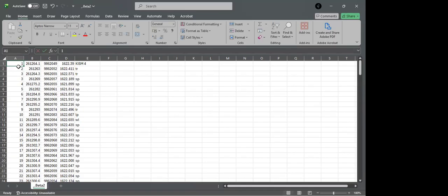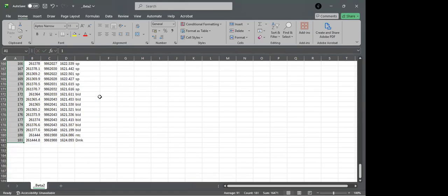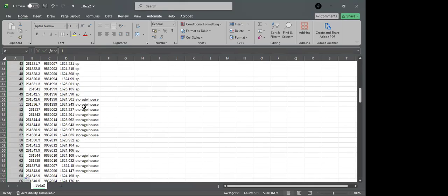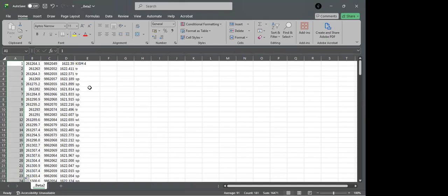Then we check if we have any other outlier point. We fix it. Then we upload the elevation. It's okay. The description, it's okay. But remember, you want to work on the description so that you have something uniform. See here we are having lowercase, in uppercase, the benchmarks, and whatnot. So this is what we are having.